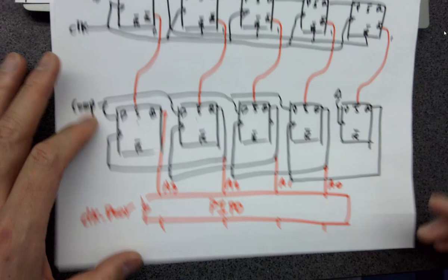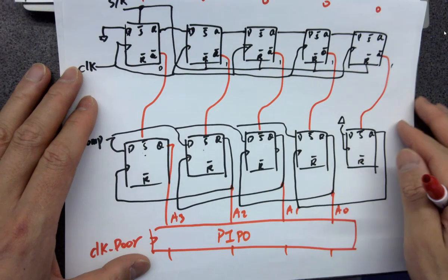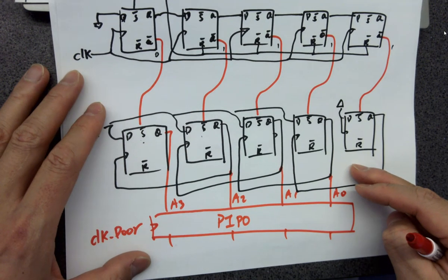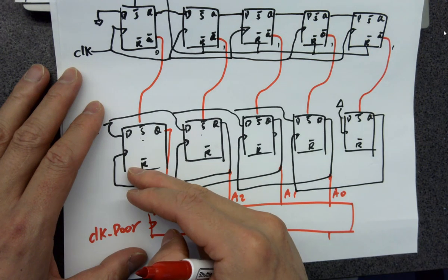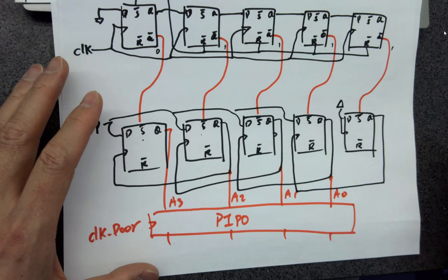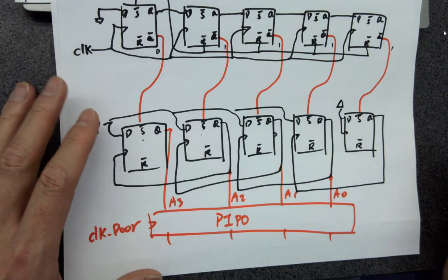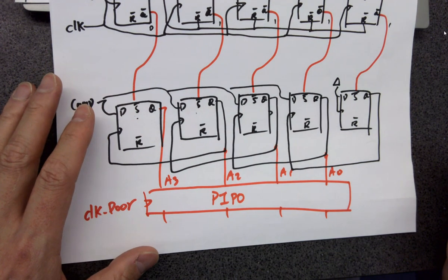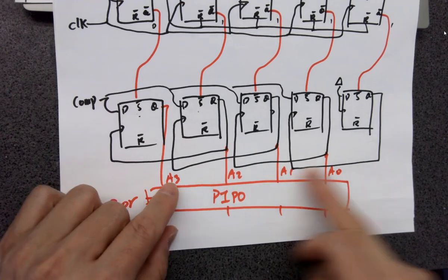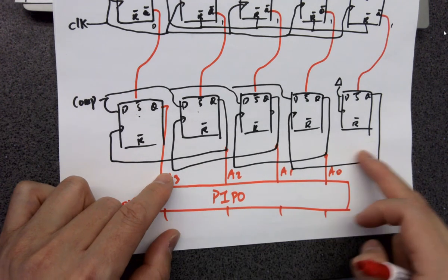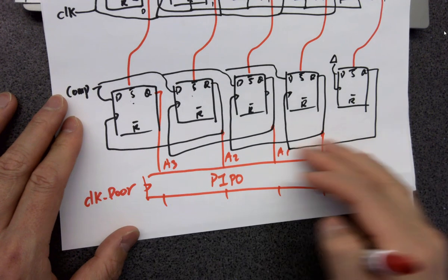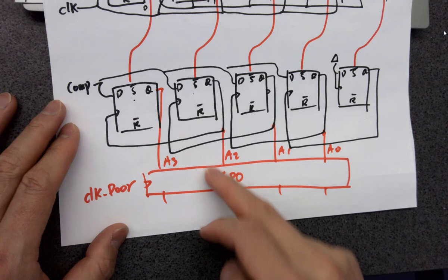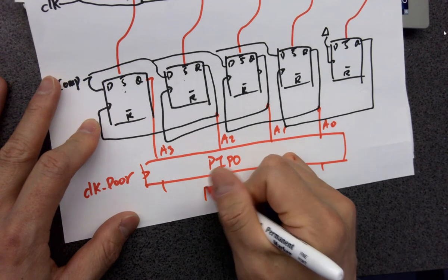Because you are having a lot of intermediate values over here, which are not the final results. During the conversion, remember for the 8-bit ADC, you have like 9 intermediate states, and these are not final results. All of these are being shifted, so the results are changing. And eventually, you know that you got the final results ready, you just kick it out to the output. So this is the final output.